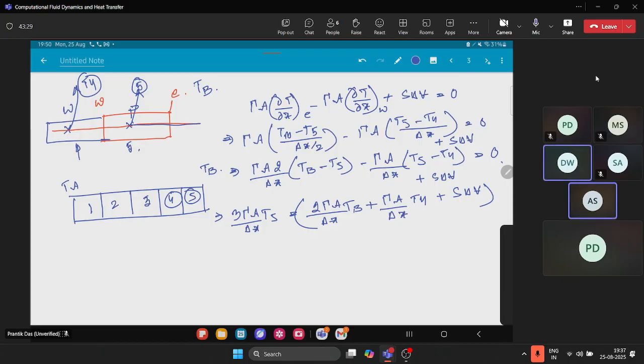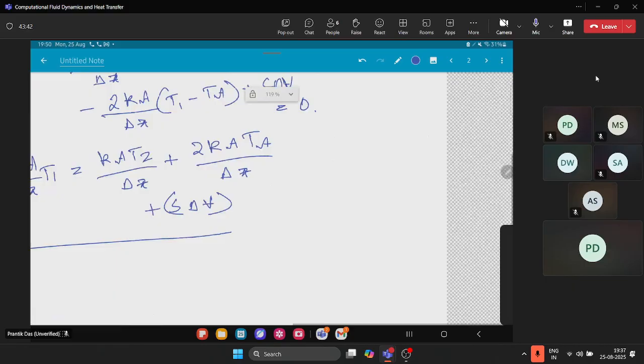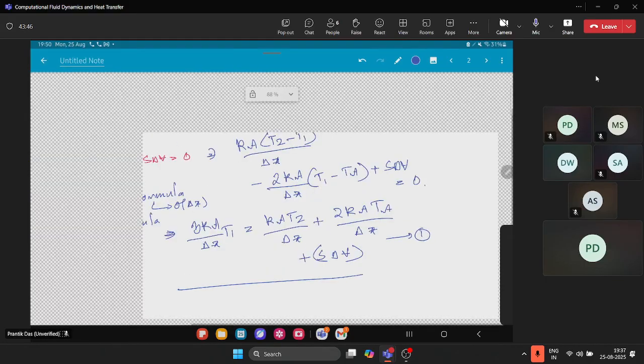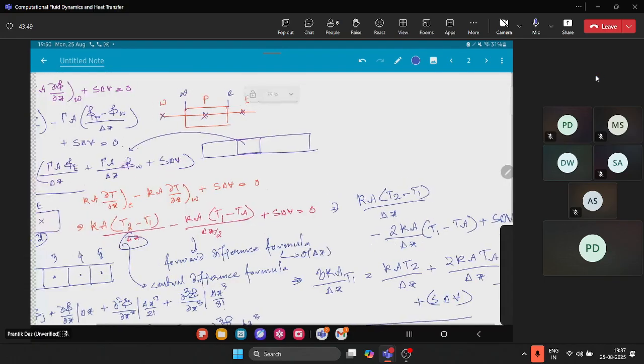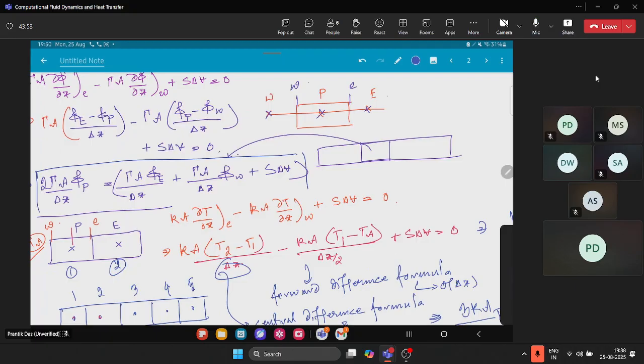Yes. Okay. So now what I will do is convert this set of equations into matrix form. This one is the right hand side cell centroid, the fifth one. If I go to the previous slide, this one is for the first cell centroid, and for a general cell centroid at the interior of the domain the equation is this one.